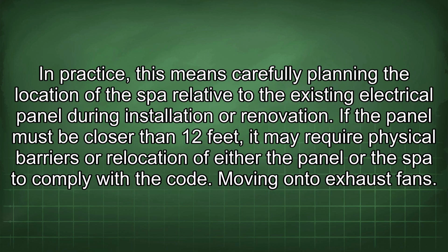In practice, this means carefully planning the location of the spa relative to the existing electrical panel during installation or renovation. If the panel must be closer than 12 feet, it may require physical barriers or relocation of either the panel or the spa to comply with the code.